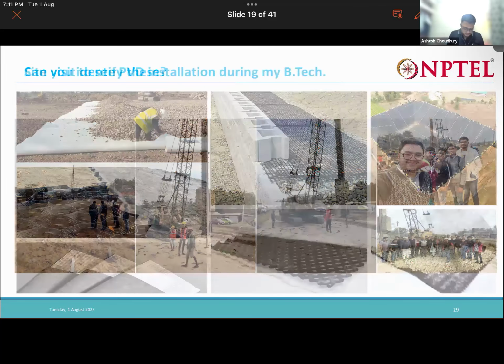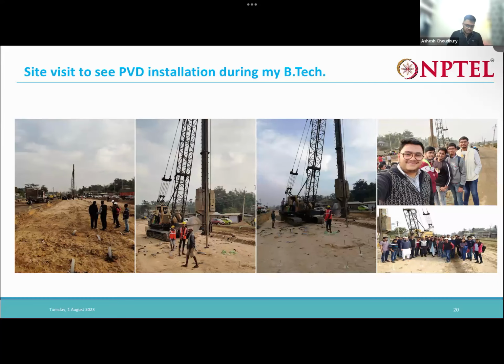Okay, so you can see this is the drilling machine using which these PVDs are installed. These are the PVDs that are installed. Proper design has to be made for the distance and the arrangement of the PVDs.